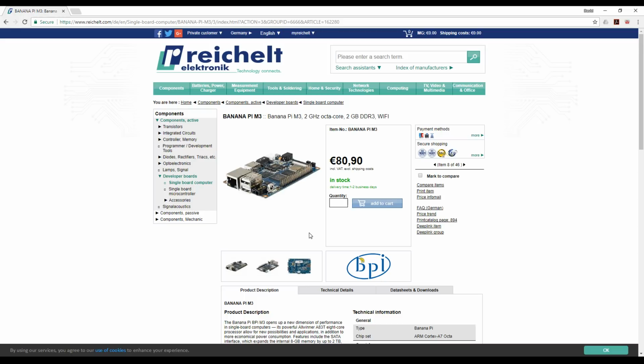But that was because of the software and the weird power requirements. Like, it was so fussy with power, more fussy than any other board I've worked with. I'm hoping the Banana Pi is not going to be quite so bad with power. Like with a Raspberry Pi, you can literally power it from a power bank. You can stick a few AA batteries together. You might get a little warning thing, but at least it'll boot up all the way. But the Orange Pis seem to be terrible for it.